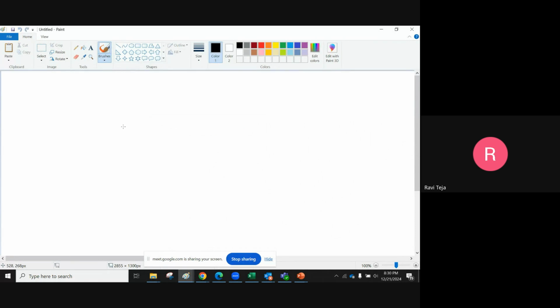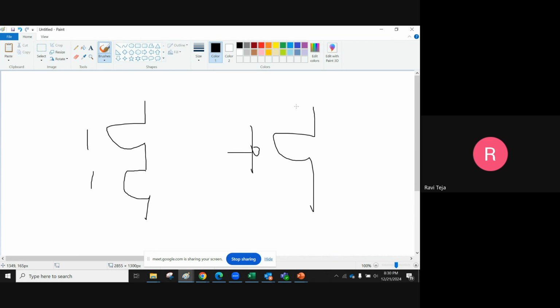while they are doing some transistor modeling, every designer will have, if I take a PMOS here, this is PMOS, so source and drain. So every designer will have capacitance readings for this. This is called transistor modeling, like source to gate cap, and gate to drain cap and everything. They will have this modeling, and then they will start designing their schematic.